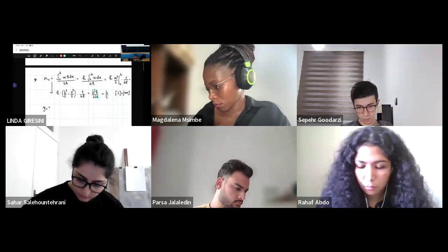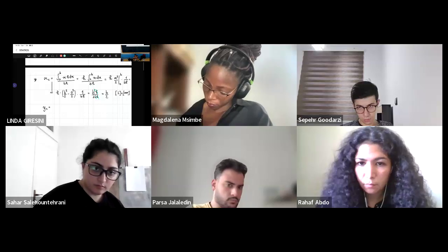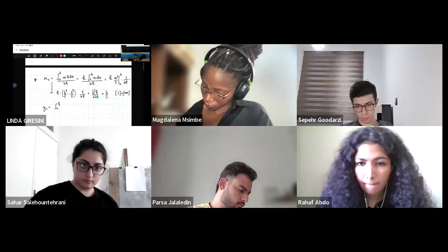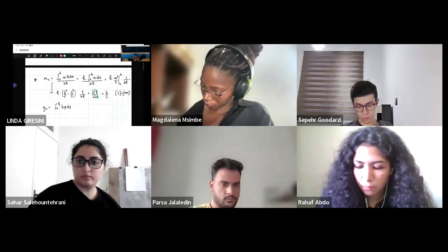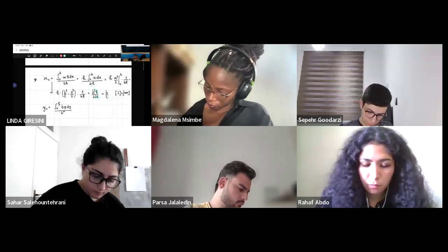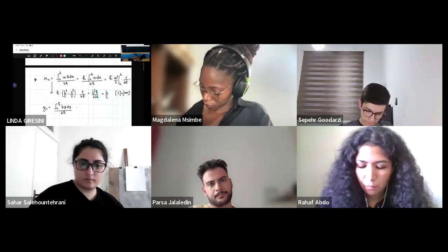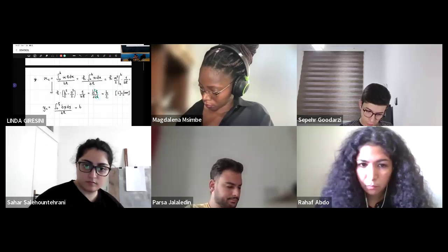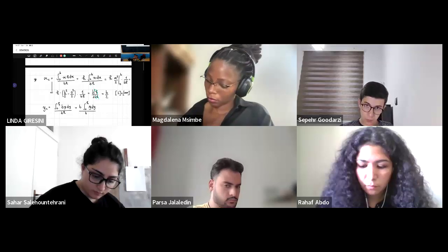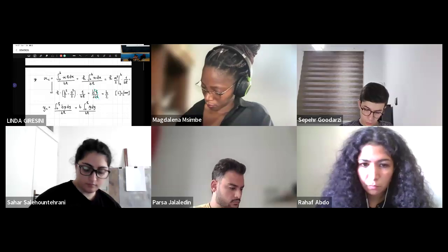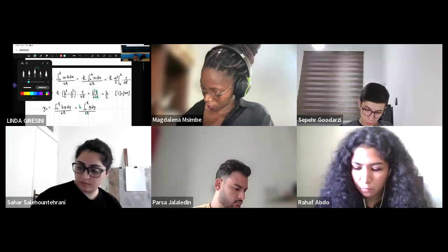Now, YC, the centroid, considering the vertical axis, so it will be integral from 0 to h of y times b dy. I'm just copying what is written at the top. Divided by bh. This time b is constant, so I can put it outside the integral. Integral now from 0 to h of y dy divided by bh. Actually, still we can simplify the b in here.